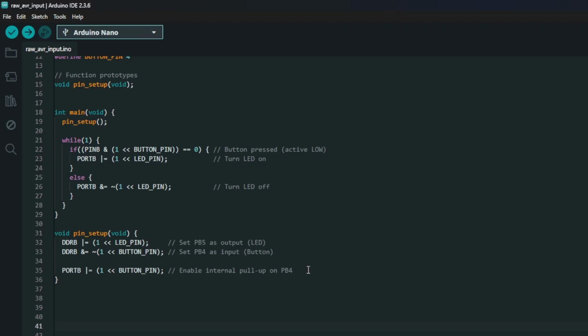We need to enable pull-up on the button pin, because the microcontroller will read this input, of course, and this pin that we connect the button to can pick up some very low or very high frequencies. These frequencies are considered noise. They are not what we want. This noise essentially will make our pin be either 0 or 1. It will oscillate between these values. It's 0, after 1 second it will be 0 again, after 1 second it will be 1, for example. This is purely random, we don't know that, and we don't need that.